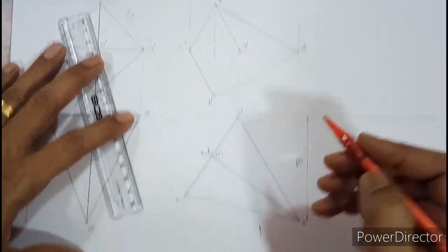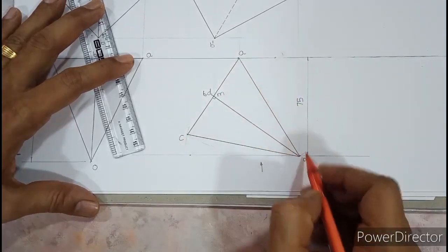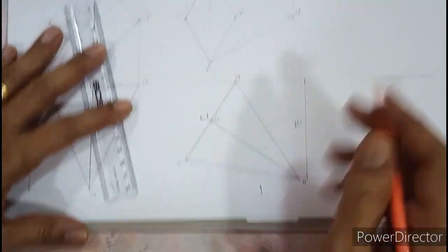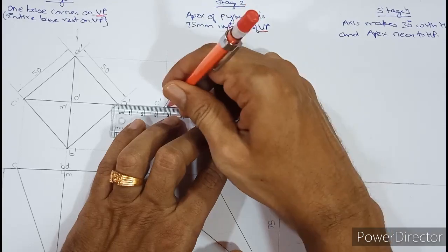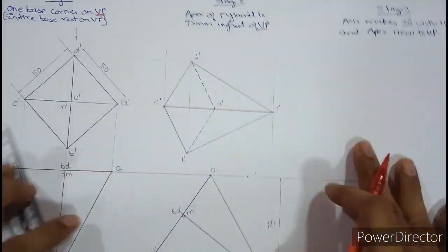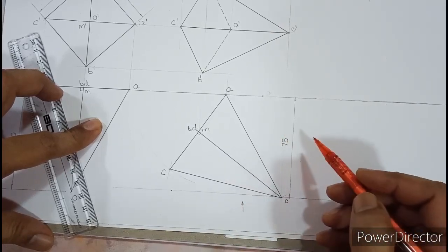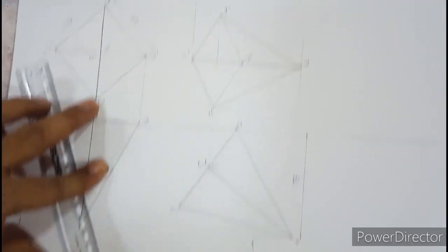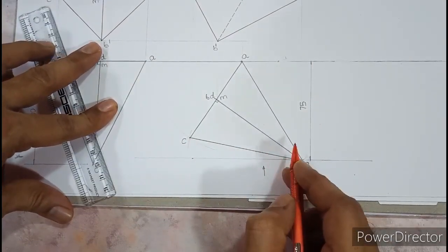How will you understand? Look at this diagram. So look from this side. Compare OC and OA. Because you can see within 180, OC will be dark. So let us draw OC dark. Okay, now you cannot see OA from this side because it is beyond 180. So there is no point in drawing a hidden line now because it overlaps. So what comes first from here? This is the observer. So first comes OC. So we have to draw that.